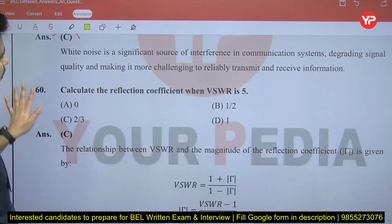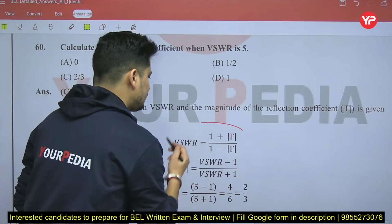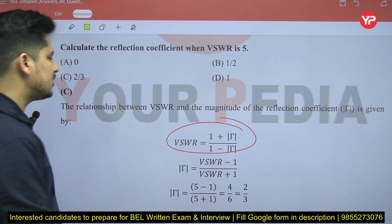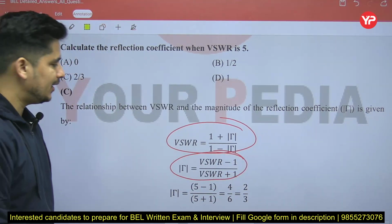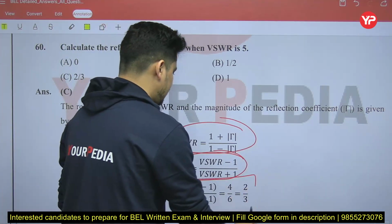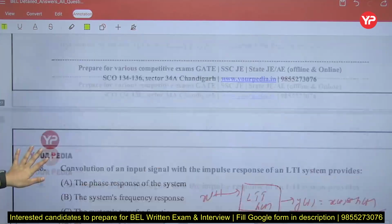Calculate the reflection coefficient from a VSWR. So VSWR is what? 1 plus mod of reflection coefficient divided by 1 minus mod of reflection coefficient, and from this one we get that the reflection coefficient is (VSWR minus 1) divided by (VSWR plus 1). So from this one we get the reflection coefficient, that is 2 by 3. That is the easy way. Next.